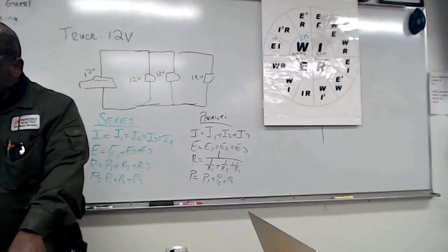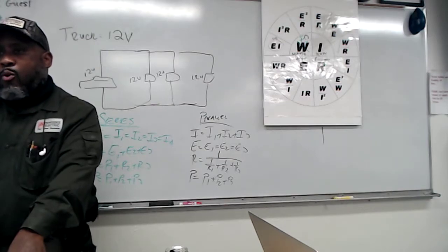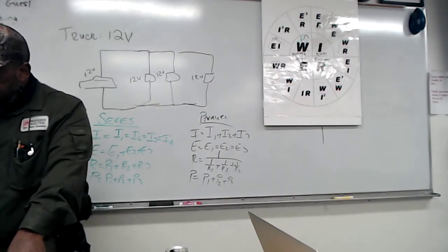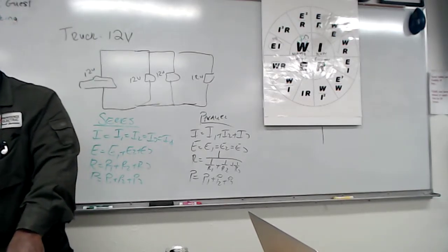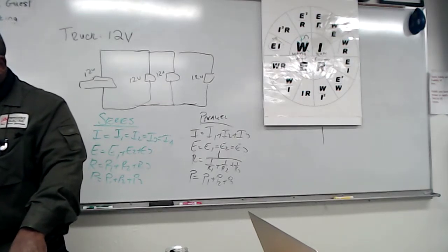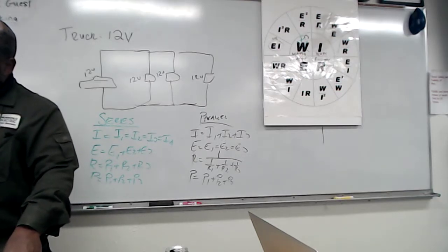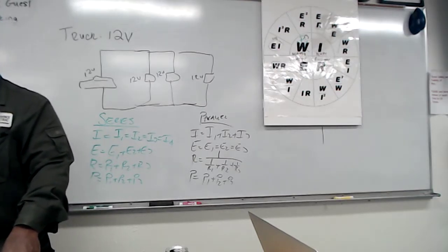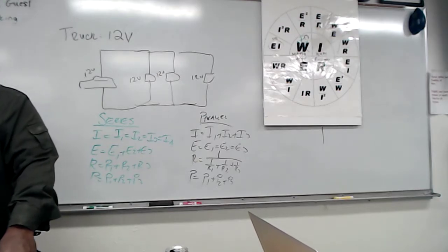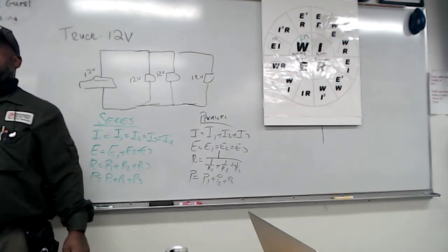Look down at the notes. You see the notes underneath the table? There's a little place to say notes. You see that? Number 1. It says Section 310.15(B) shall be referred to for correction factors where the ambient temperature is other than 30 degrees Celsius, 86 degrees Fahrenheit. So what I want you to know is this table is only good for 86 degrees Fahrenheit, in a sense.